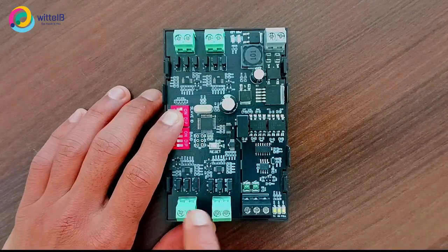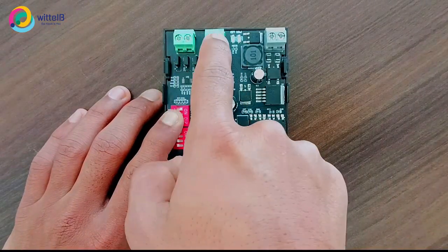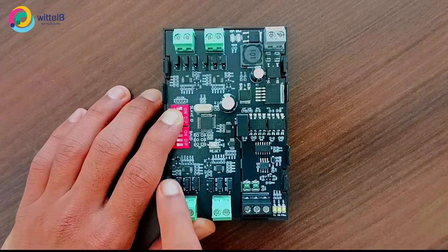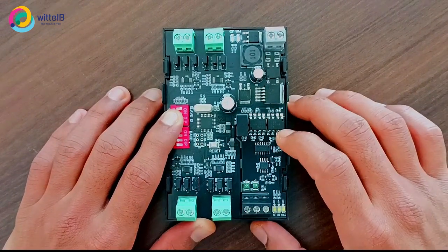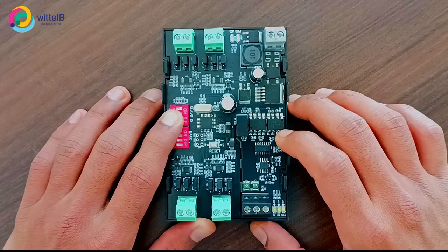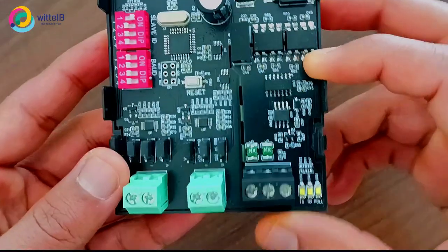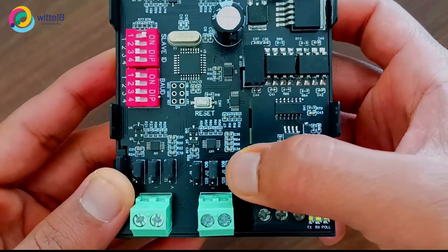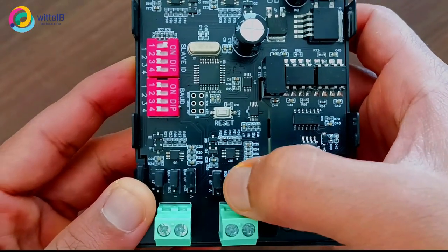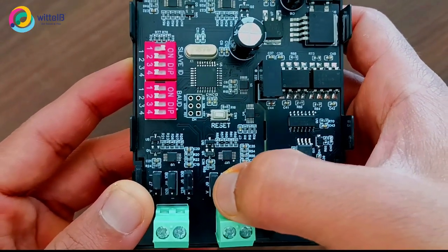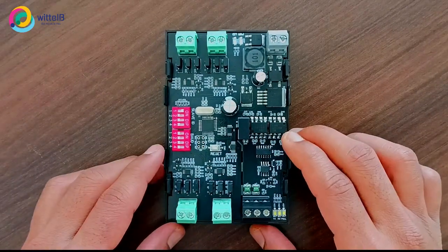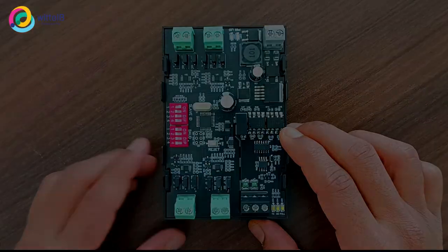Here we have 2 AO part, and here we have 2 AO part, a total of 4 channels for the analog output. In this AO part we have the jumper provision. Here we have 10 bit and 12 bit, and you can set voltage and current also. In the jumper we have marked the voltage 10 bit, 12 bit, and the current 10 bit, 12 bit. Just by shifting the jumpers you can set voltage or current, and also the 10 bit or 12 bit resolution.